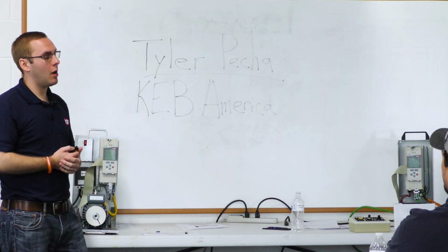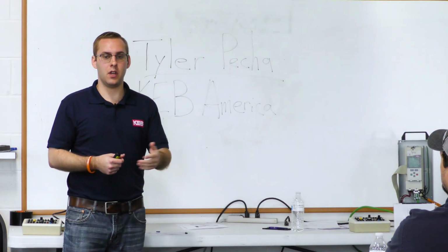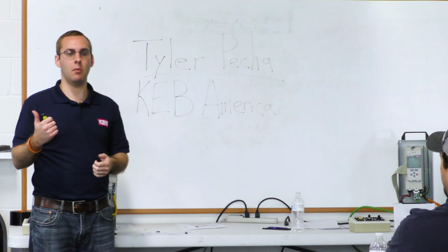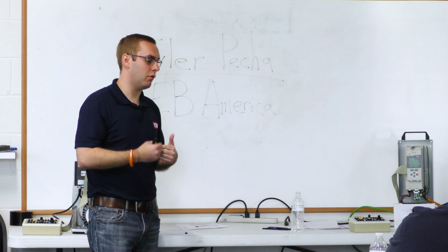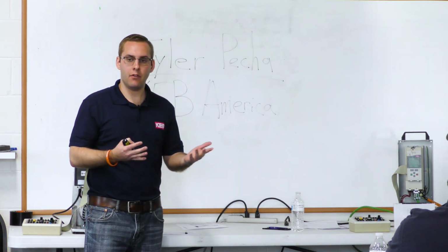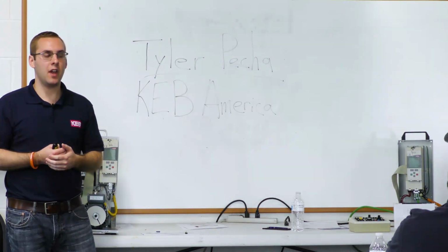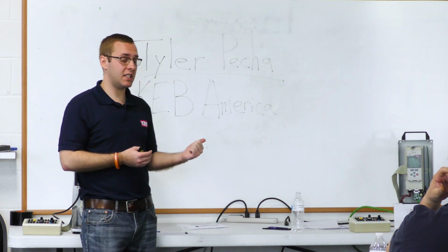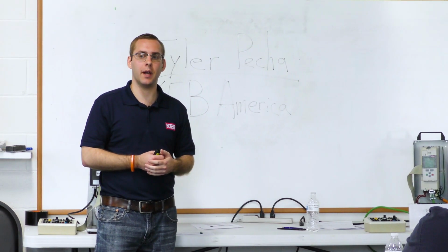So if you power up independently, that way if you do blow them again, you know that when you hooked up the drive, it was the drive that was causing it, or it was when you hooked up the motor. Also, another thing to take one more step to avoid blowing the fuses again is to do a diode check on the drive. Anytime you blow fuses on the regen, always do a diode check on the IGBTs of the drive. That way, if one of them is blown and we see it on the diode check, you can save yourself a set of fuses and get that fixed right away.